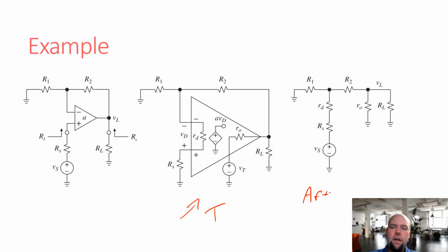A lot of students often ask how you generate the equivalent circuit. Really, for finding this return ratio, you need to break the circuit right at the output of that dependent supply internal to the op amp, and you then hook up a test voltage here.